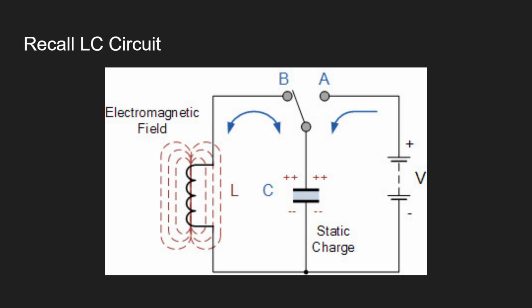Okay. So XL and XC, when they are the same, you will see that the proof is 2 pi FL equals 1 over 2 pi FC, right? So 4 pi squared F squared LC equals 1. F equals 1 over 2 pi root LC. This is how they do the resonance, okay?